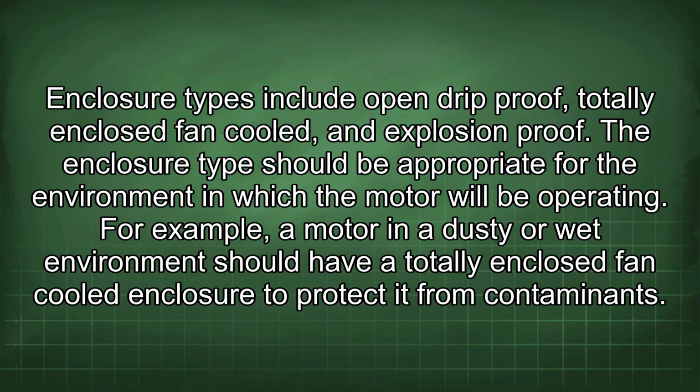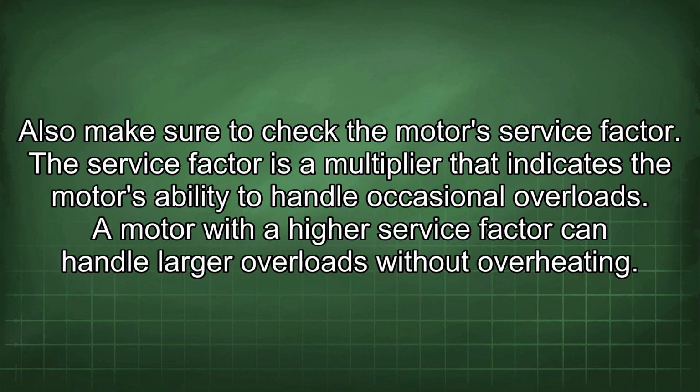from contaminants. Also make sure to check the motor's service factor. The service factor is a multiplier that indicates the motor's ability to handle occasional overloads. A motor with a higher service factor can handle larger overloads without overheating.